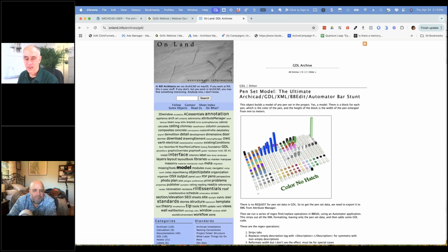So you can basically have repetitive battens, and you can then put in some things that would cut out openings. Yes, you can. Now, if you have multiple openings, I think it limits you to 8, and you can specify the sizes and then move them around on screen by clicking on their borders and moving them. I've had it where I might have more openings, and I might have to split it up into 2 of them so that I can have additional openings if I had a large surface.